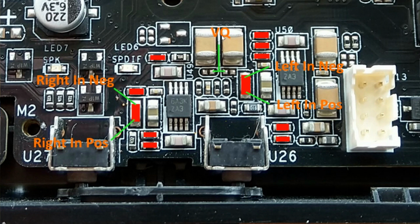So this is the center voltage reference. It's on both these two pads here. And the right side negative is on the top pad here, right side positive the bottom pad, left negative the top pad, left positive the bottom pad, where this capacitor that's been removed was. And to get the 5-volt supply voltage, we can just take it across one of these power supply decoupling capacitors. Here is plus 5 volt up here, and ground down here.